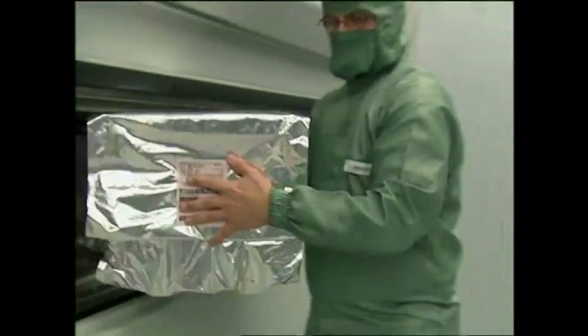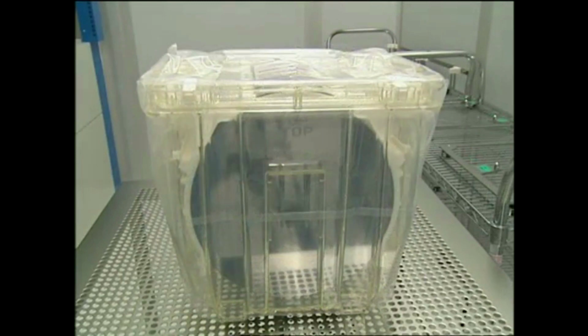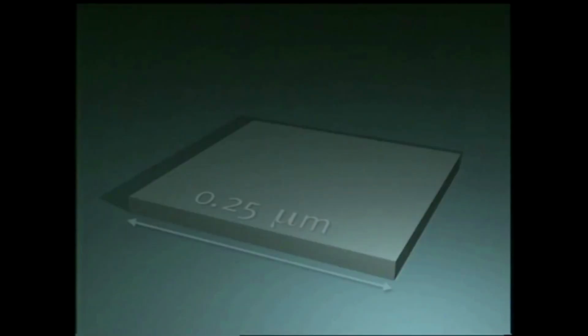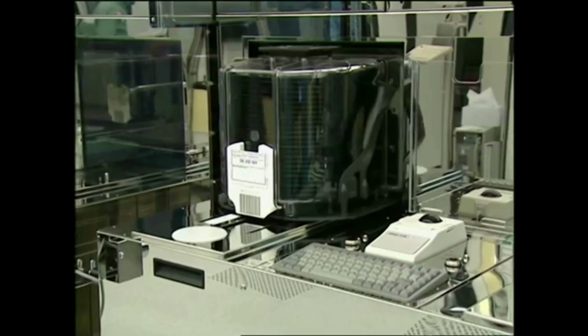The basic material for the chips is a 1 mm thick silicon wafer. This is a tiny cutout of a wafer edge, 1/4 of a micrometer. First, the conductive or non-conductive layers are produced by oxidation of the surface at approximately 1000 degrees Celsius. In a high temperature furnace, a drop of photoresist is uniformly distributed by centrifugal force on the oxide layer produced, thus creating a light sensitive layer.